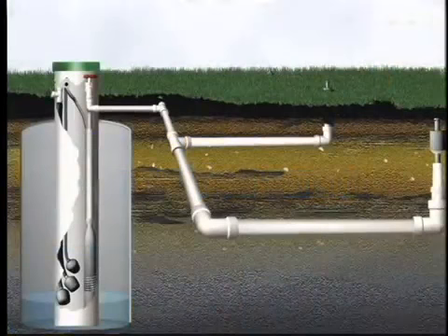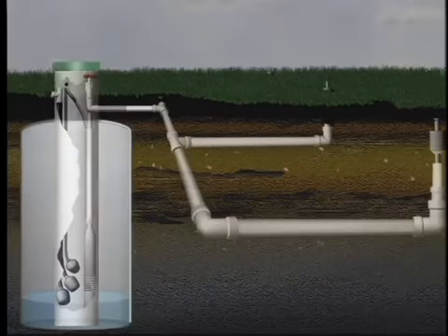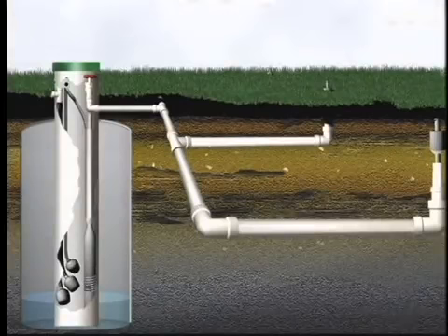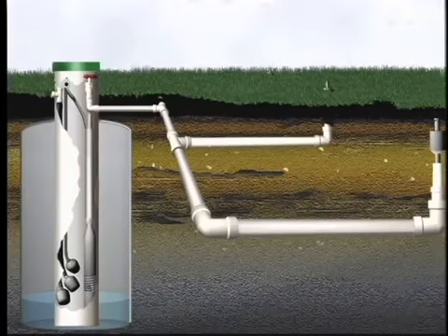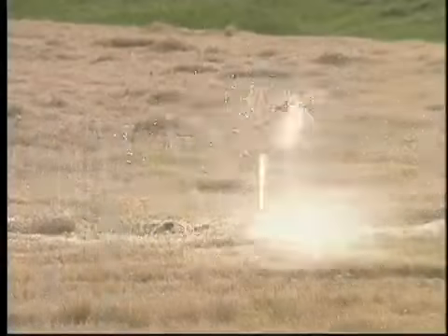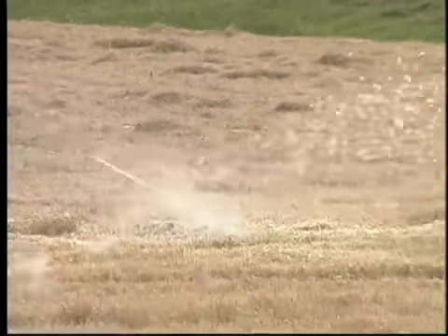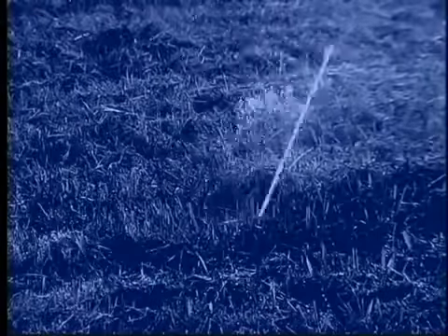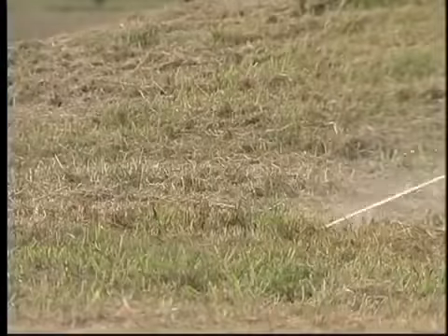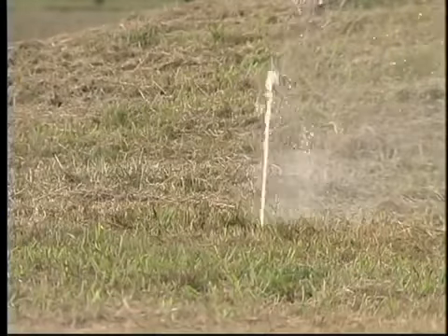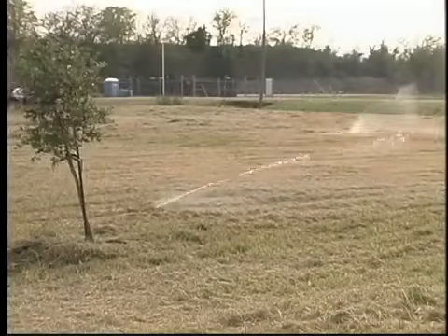A spray dispersal system utilizes a pump tank, pump, and spray heads to distribute wastewater on the surface of the ground. The pump tank stores the water until it is time to dose the water to the spray area. The system can either be an on-demand system, which sprays the water whenever the tank is full, or a night dosing system, which holds the water until night and then the water is dispersed. Most residents prefer a night dosing system when the effluent will be sprayed in the landscape. These systems distribute wastewater across the soil surface much like a traditional lawn irrigation system.